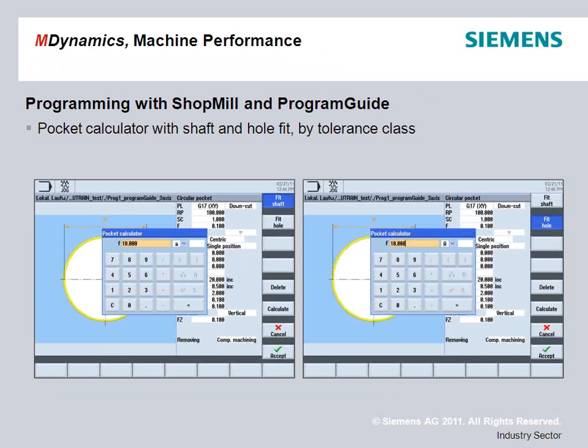In terms of other things that they can do, if you need to make bores or bosses that have to do press fits, we do have a fit calculator built into the control. So you can give it the nominal diameter and also give it its fit class by letter grade. The control will calculate these for you. This would be another case when it's important to give the tool data, set up all the information about the tool. This is again a job shop and one-off targeted feature.